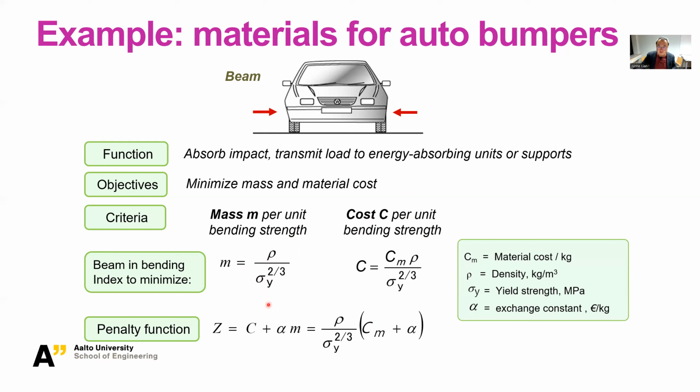That's why we formulated with the material index concept, if you still remember. But pay attention here, the material index is formulated differently. In the material index for, let's say, as light as possible and as high bending strength or stiffness as possible, we actually usually put the sigma yield 2/3 or 1/3 into the numerator. But here, we're not in the numerator, but in the denominator.